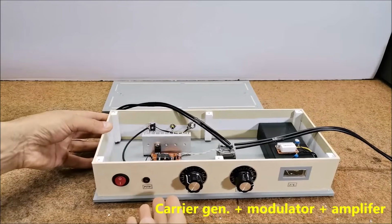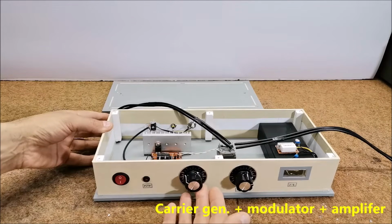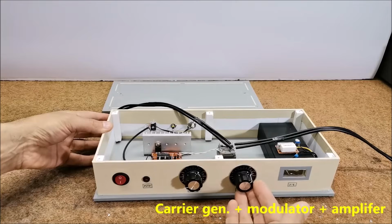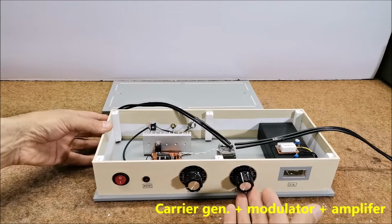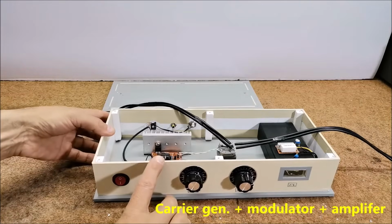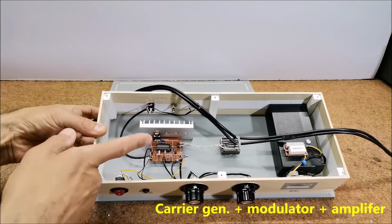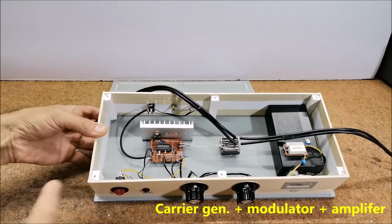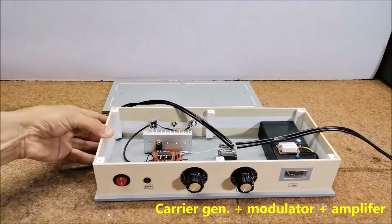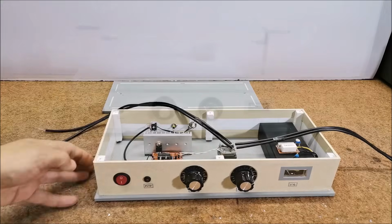With the first potentiometer the degree of modulation, the gain, is regulated, and with the other the carrier frequency. We can change the carrier frequency in the range from 20 to 200 MHz. Then this modulated signal is amplified by a power transistor, which is mounted on an aluminum board for cooling, and fed to the primary windings of a high voltage transformer. The circuit diagram for this part is given in the project attachment.